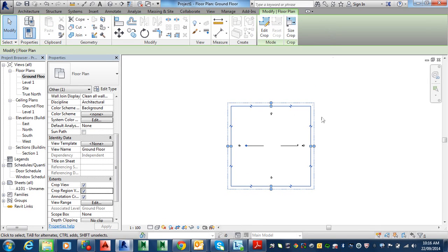So basically, you draw your little house in here. You don't want a big viewport around it, because when you drag it onto the sheet, it draws that rectangle around it and takes up space for no reason. It looks a bit messy. So before we print, we'll turn this on and drag it back to the size of our house, nice and snug around the house.